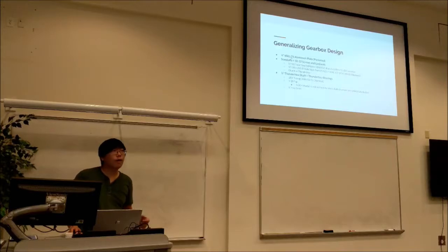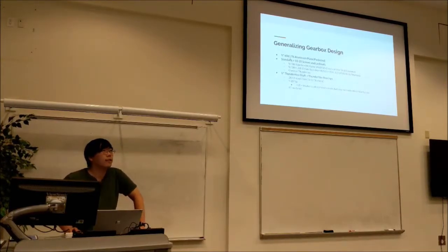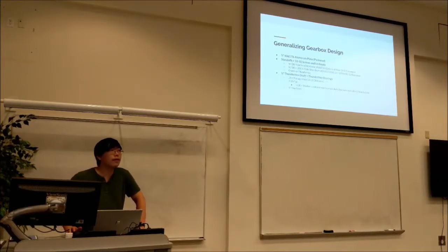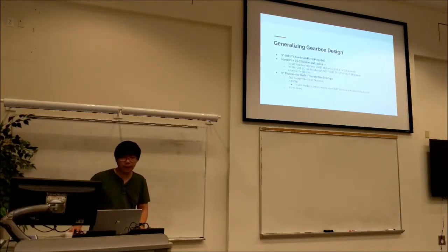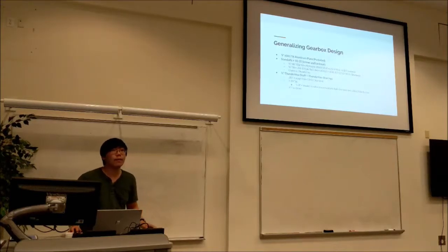For our team, we particularly use quarter-inch 6061 T6 aluminum, and we do pocket. And then for the standoffs we standardize using 10-32. 10-32 is a type of screw size if you don't know. The reason why we do that is because VEX, WCP, and AndyMark also use 10-32 in a lot of their parts. So if you standardize using 10-32, you'll have a much easier time in terms of repairability.